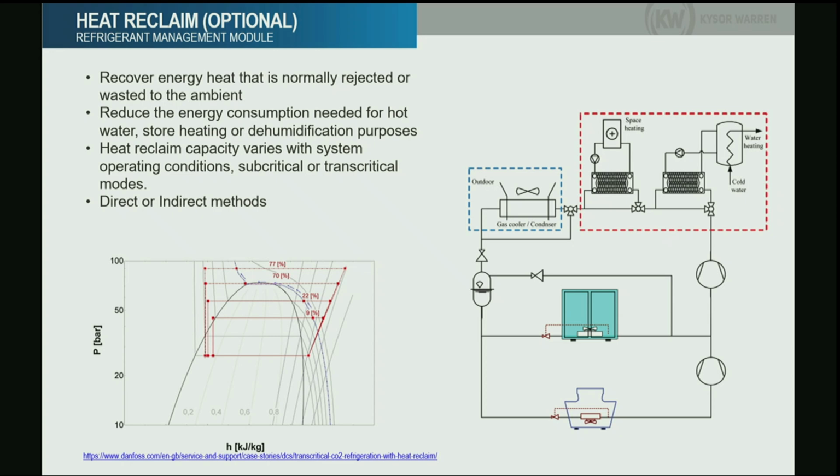We can do that artificially with the valve and the controls. However, that is not free. We will be penalizing the compressors because they will be running at higher pressure when they don't need. So that's a balance again. We want heat, yes, but how do you want to pay for that? With the compressors or with another kind of heat? It's not free. But it's a possibility that you can use there.